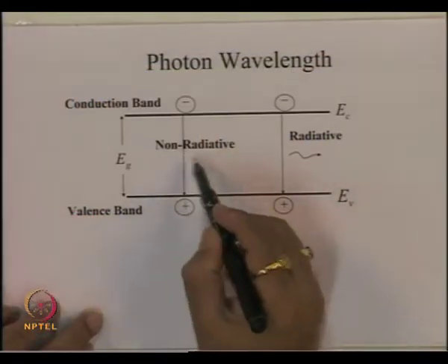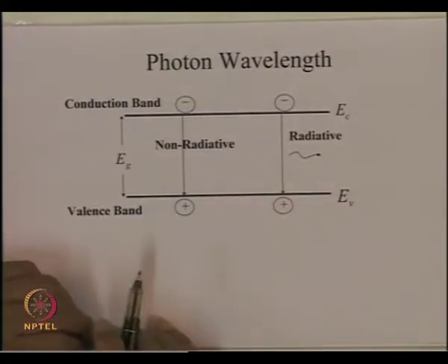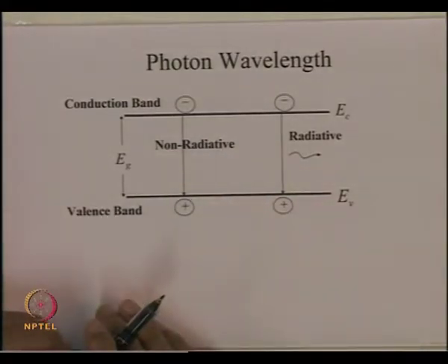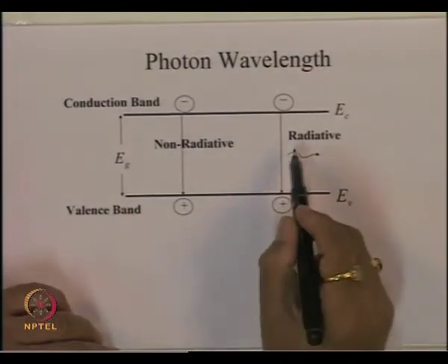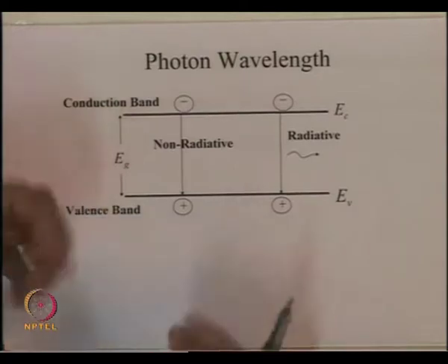If a photon is released, then we call that recombination process the radiative recombination process, and if the photon is not released, if the energy has gone into some other form, then we say that process is a non-radiative recombination process. So, whenever we have electrons and holes in a semiconducting material, and when they recombine, part of the recombination will not produce photons and part will produce photons. The ratio of the recombination responsible for photon generation to the total recombination which takes place is essentially what is called the efficiency factor. We will discuss later how many of the total recombinations go into radiative recombination.